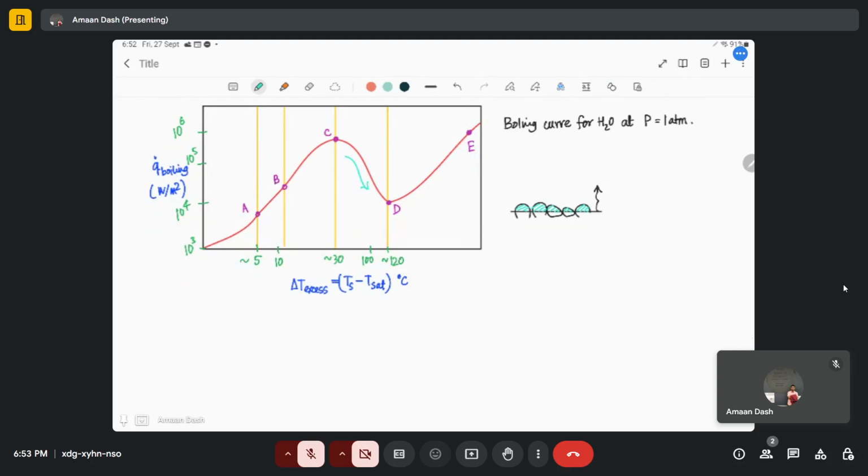For dropwise condensation, only a fraction of the surface is exposed directly to the environment, whereas for filmwise condensation, a blanket of liquid film adds extra resistance to the transfer of heat. Therefore, it lowers the heat transfer from the surface.